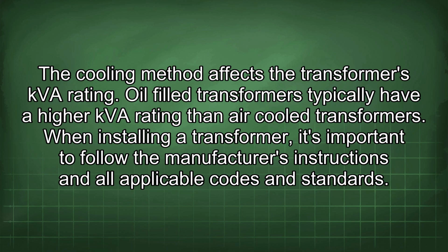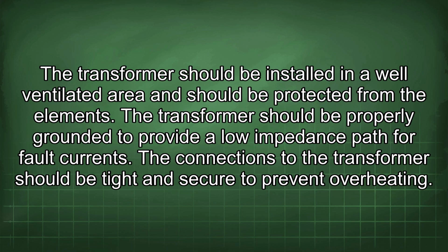When installing a transformer, it's important to follow the manufacturer's instructions and all applicable codes and standards. The transformer should be installed in a well-ventilated area and should be protected from the elements. The transformer should be properly grounded to provide a low impedance path for fault currents. The connections to the transformer should be tight and secure to prevent overheating.